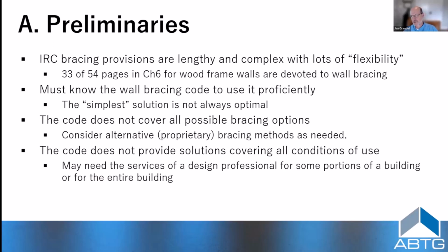And so there's a lot of rules that need to be applied, and they're applied to every single bracing method. Now, the bracing methods may have different properties, and the rules have different values assigned to them for different products, but they're all based on the same principle. So if you use any of the bracing methods correctly, you get a building that has equivalent overall lateral capacity, which is our goal.